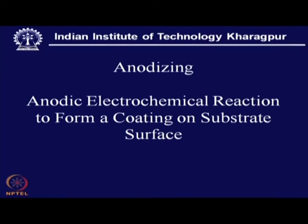Now, we have to consider anodizing. In fact, anodizing means it is actually what we call electrochemical dissolution. That means, the reaction on the anode side is not add-on, the material is being continuously donated and the anode will lose its mass, that is what we understand.